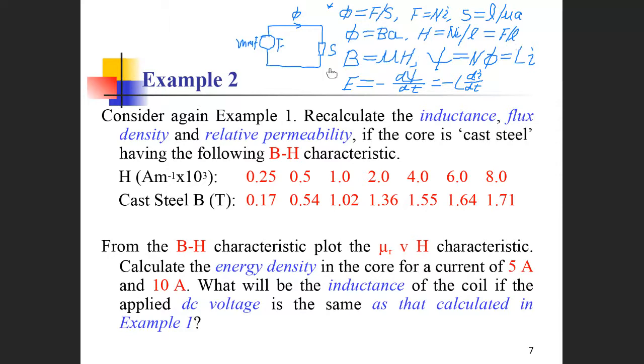And then the magnetic flux density B and the magnetizing force H are linked by the so-called mu, the permeability. So in practice, we do experiments to get the relationship between B and H. Look here: B determines phi, phi determines the big Phi, and the big Phi determines the induction. The induction is the voltage.